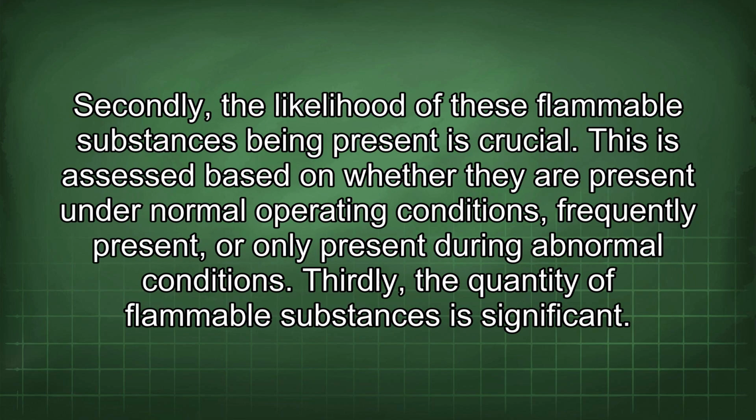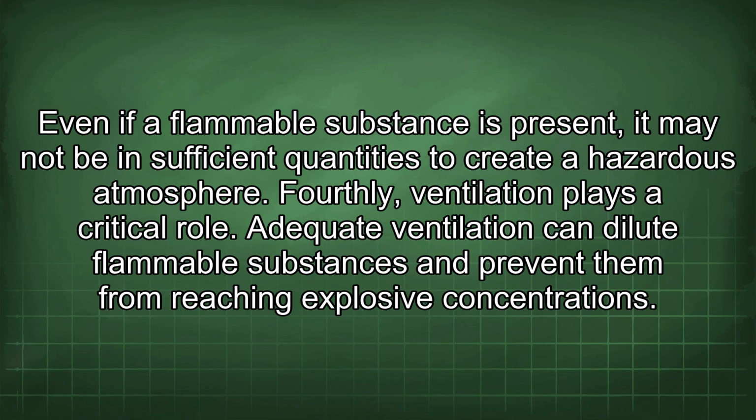Secondly, the likelihood of these flammable substances being present is crucial. This is assessed based on whether they are present under normal operating conditions, frequently present, or only present during abnormal conditions. Thirdly, the quantity of flammable substances is significant. Even if a flammable substance is present, it may not be in sufficient quantities to create a hazardous atmosphere.